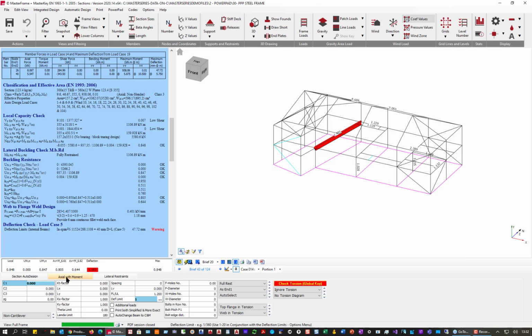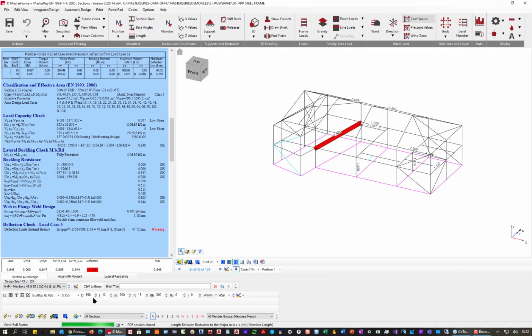So what do I need to do? Well, in this case you need a bigger section, Tommy. So let's go back to the plate and we can see we can squeeze it out to 600. Just type that in, 600. We're still failing. We're going to increase the web to 15 and we're still failing.